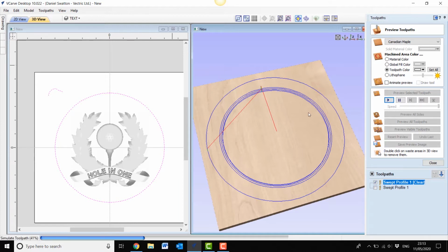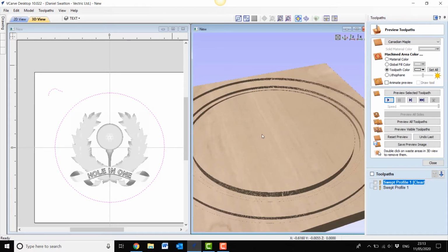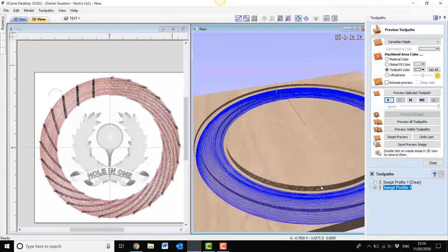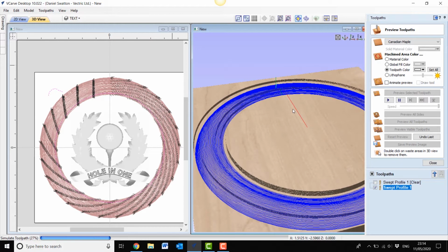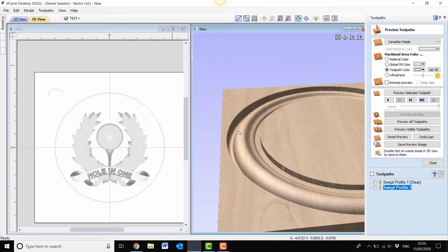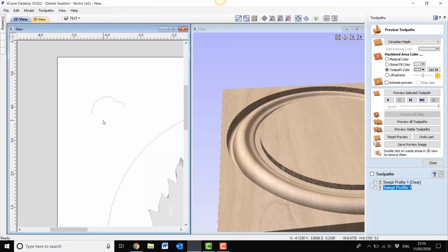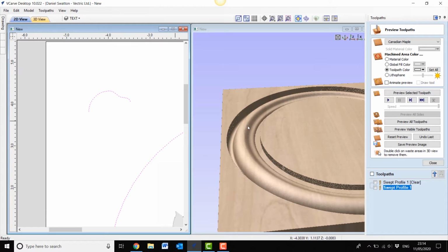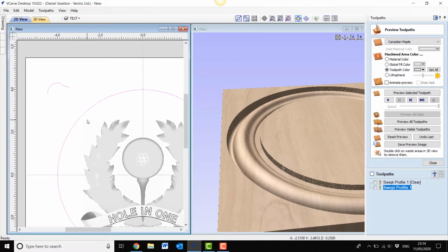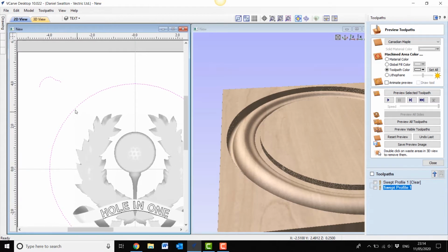With that, I'm going to show that in the simulation. So I'm just going to play that. We can see the initial clearance, and now come down and select the finish for the actual molding shape, and we'll apply that in the simulation as well. And this should show a really nice 3D form that, as you can see there, closely follows the 2D cross-section view that we've got on the left-hand side. We now have that in 3D form when we create the toolpath and simulate it, which is a really great tool because it has saved us the need to physically create any component, and we also have the toolpath following the actual direction of the molding technique.